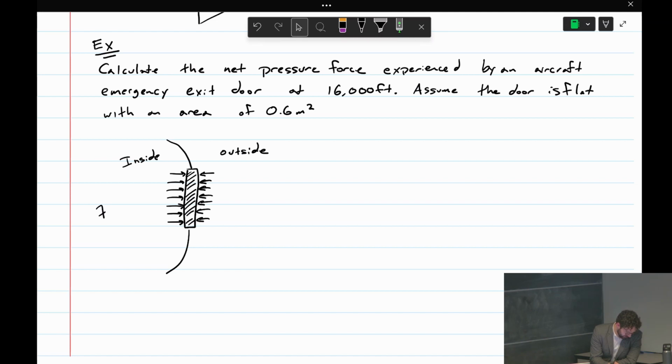So inside that pressure for 8,000, I think this is 8,000 feet, but I'll just give you the atmospheric pressure there. So 75.3 kilopascals. And sea level pressure is roughly 100 kilopascals. So the pressure that they normally keep the planes at is a little bit below sea level pressure. That's part of the reason that people tend to swell on airplanes, because the pressure is lower.